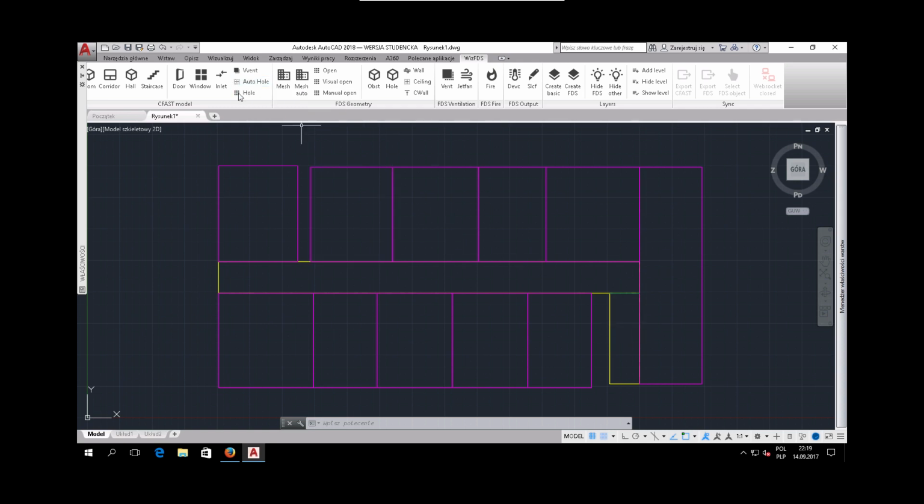Now we would like to create doors. So we select doors, and once again we need to select the Z-min, this one, and Z-max for the door. This is 2 meters for the door. And then the type of the door, because we have different distributions describing the opening fraction and the closing fraction of the door, so we can choose the plain door, door with door closer, or door with an electric unit which prevents the door from closing.